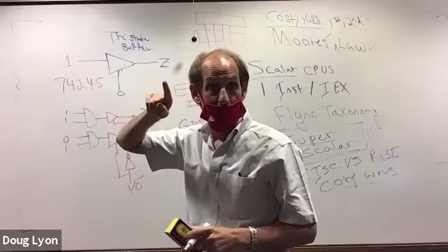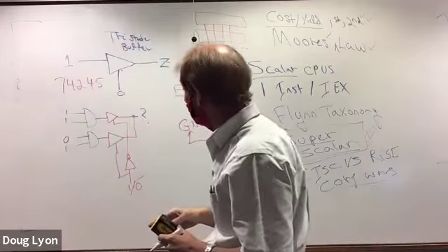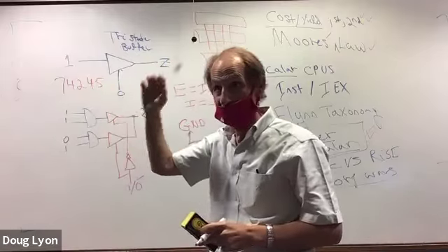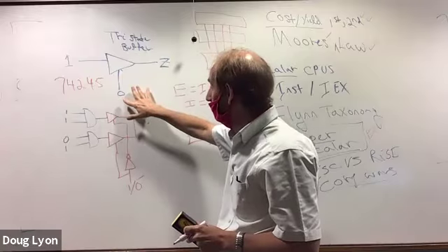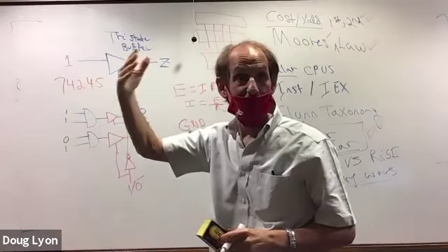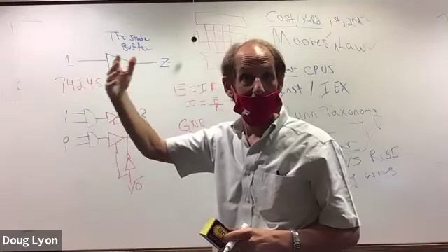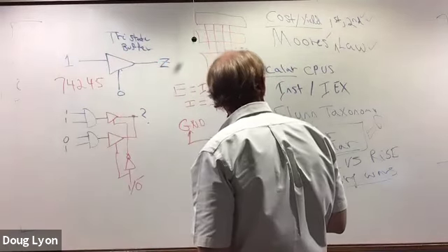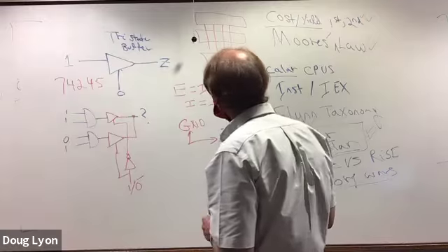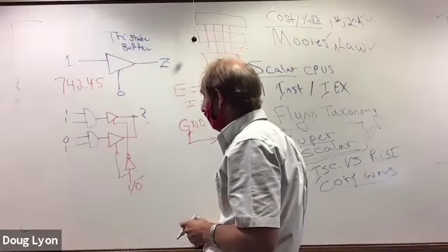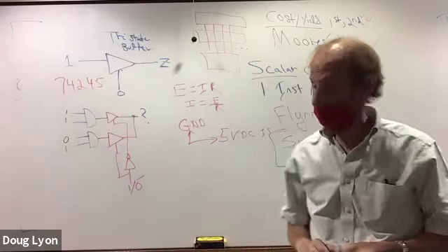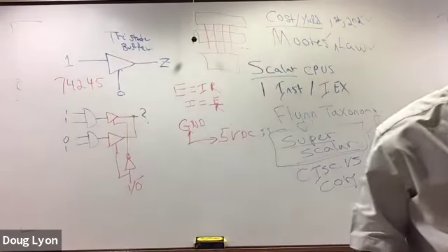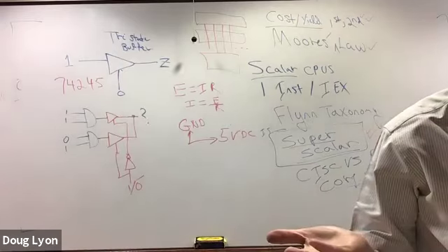And so what that means to you, the designer, is you can borrow these things and drop them into your Quartus design document and proceed to use them to create buses that allow you to address stuff like memory, or RAM, or ROM, or maybe other things that you might like to have. So the octal bus transceiver is a useful device in order for you to be able to design systems. It's octal, so it only has 8 bits.